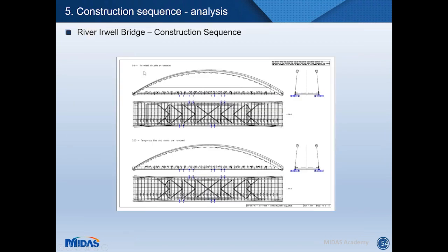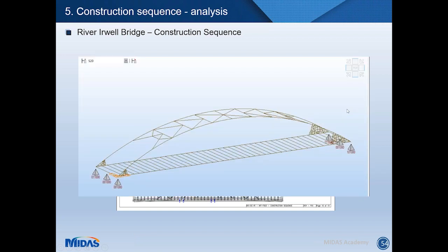Okay, it's then time to create the welded joints at the south and north end. At this stage, the arch will be fully connected and moment will be passed between the knuckle joints at the two extremes and the arch itself. And so the temporary ties can be released. Now, before doing that, as I said, there are some plates being used, bolts, and all of these need to be modeled inside our MIDAS model to follow the displacement during the construction engineering on site.